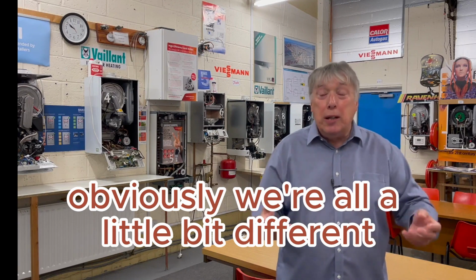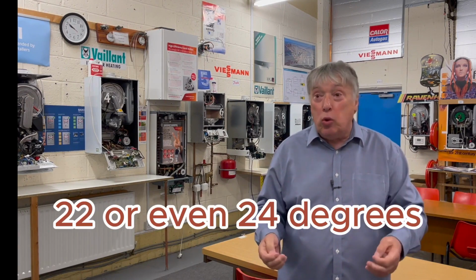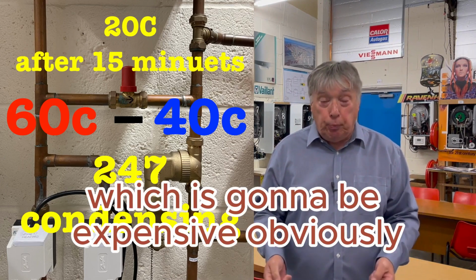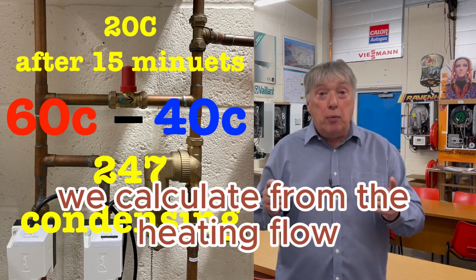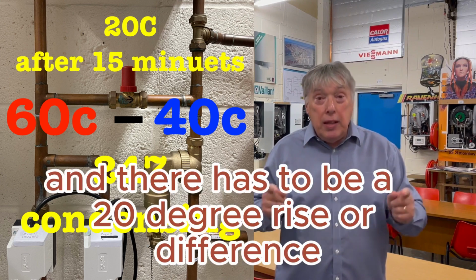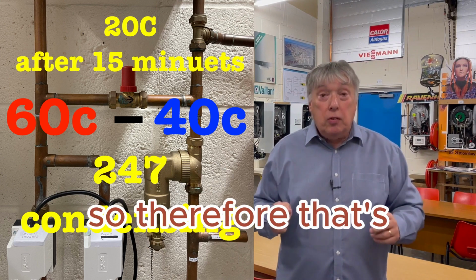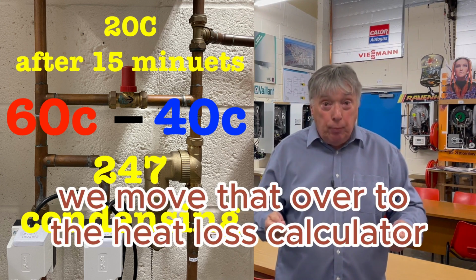Obviously, we're all a little bit different, and some people may say calculate to 22 or even 24 degrees, which is going to be expensive, obviously. The 20 degrees we calculate from the heating flow to the heating return on the boiler, and there has to be a 20-degree rise or difference. So therefore, we move that over to the heat loss calculator.